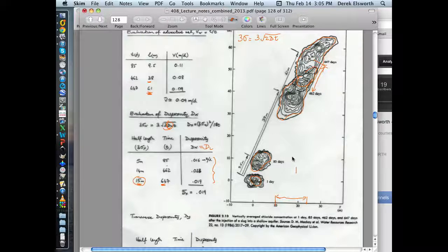The other way that we classified dispersion coefficients is due to this other expression, you'll remember, right? It is just molecular diffusion, or spreading by molecular diffusion, plus the advective velocity, or at least the absolute value of it, times the longitudinal dispersivity, I think it's referred to.